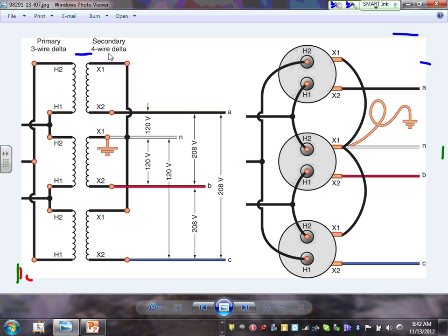Okay, what is that? It's a delta, right? No, they're going phase A, phase B, phase C to the ground. Yep, this is not a delta, right? This is a Y. Scratch this one with the Y, will you? Are you guys with me? Now, with a Y, they take all the X's to one point here, and they tie it to the ground. That's a Y. Can you change that one to a Y? This is my Y.